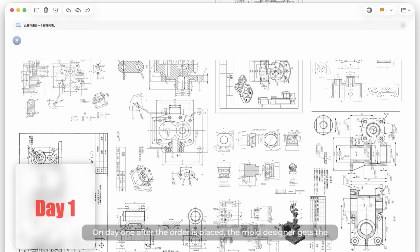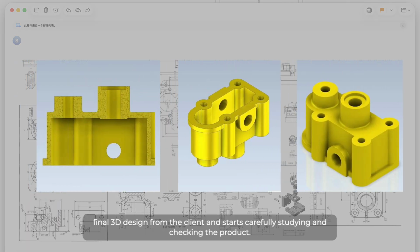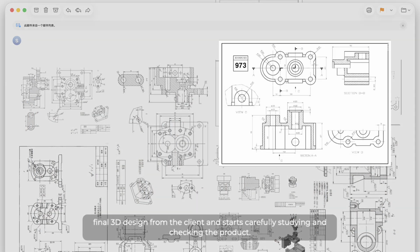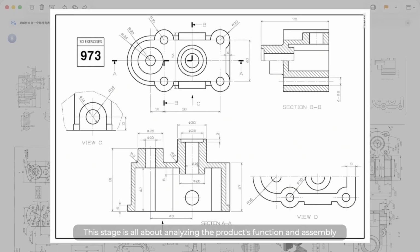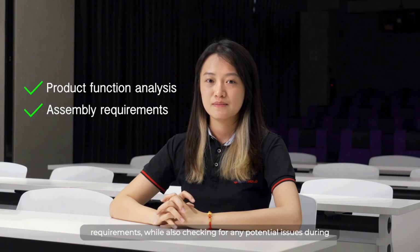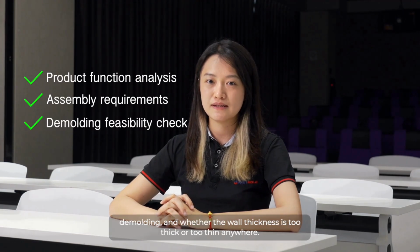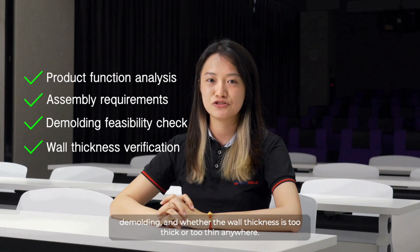On day one, after the order is placed, the mold designer gets the final 3D design from the client and starts carefully studying and checking the product. This stage is all about analyzing the product's function and assembly requirements, while also checking for any potential issues during demolding, and whether the wall thickness is too thick or too thin anywhere.